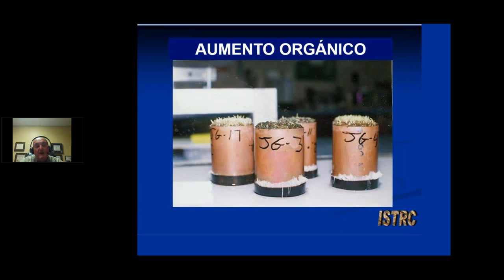When these samples came into the lab, they were flat. As part of the testing process, we put them into the water bath prior to putting them on the penetrometer, which is the device that we use to test for the infiltration rate. You can see here a good 3 to 4 millimeters of expansion on the top, and all that was strictly by hydration. The organic matter wants to absorb and expand with water, and that's a classic example of it right there.